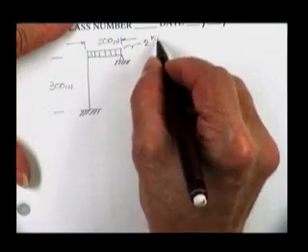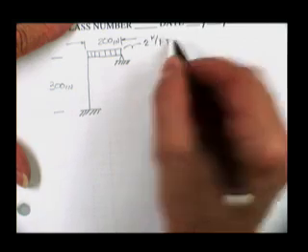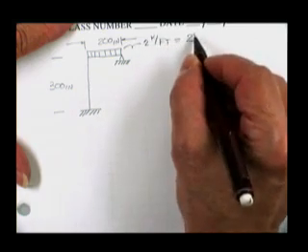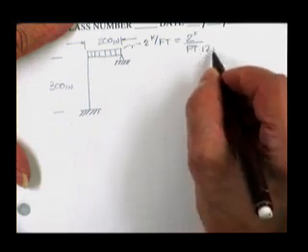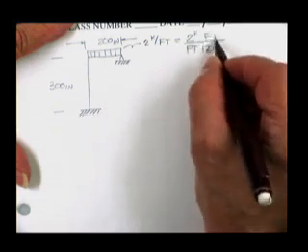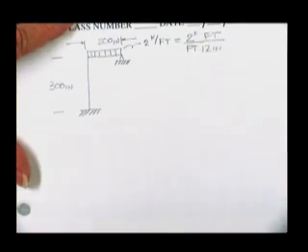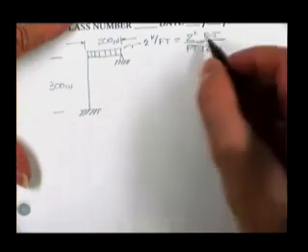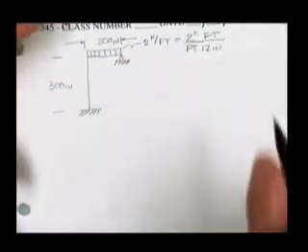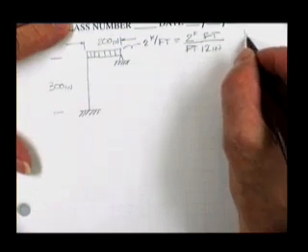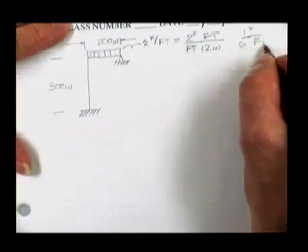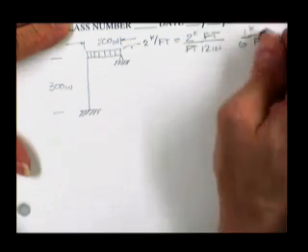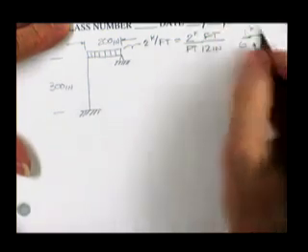2 kips per foot, which is equal to 2 kips per foot times 12 inches inside of a foot, because I've got a feeling the boss is going to give me EI in inches, so I'm going to go ahead and get it fixed now before I go any further, is equal to 1/6 of a kip per inch. Thank you. Foot cancels foot, inches.